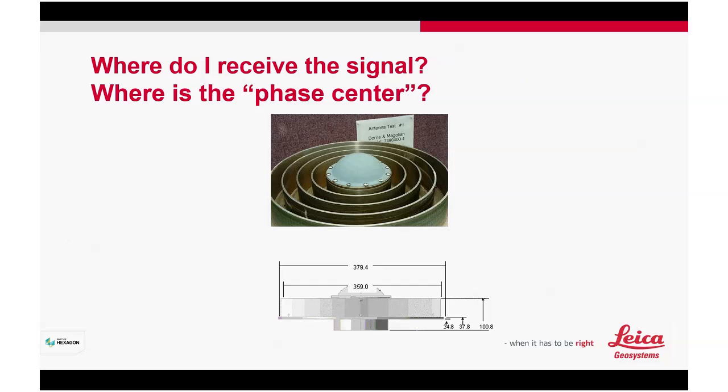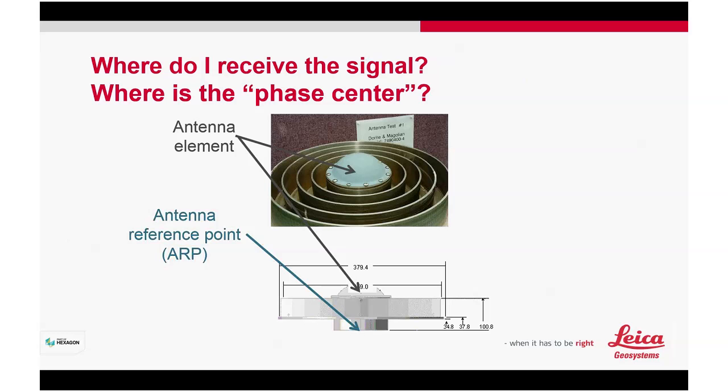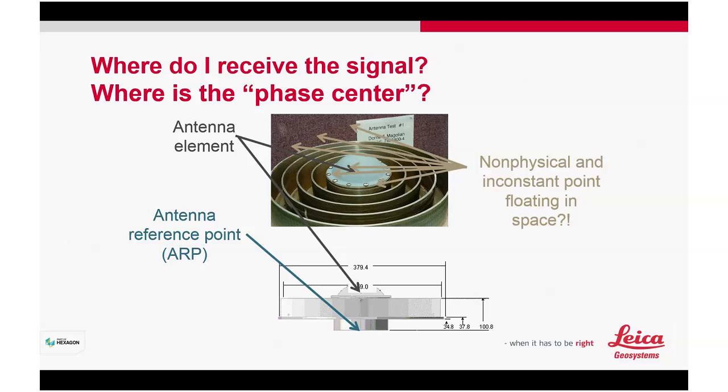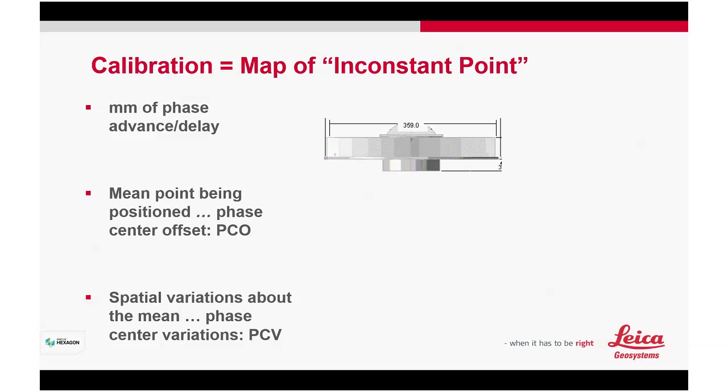Okay, so you see the antenna phase center. Okay, the question is, where is the signal we receive by this antenna? Okay, and then we have a so-called antenna reference point, or for us we call it the mechanical reference point. Okay, so there are those parameters we need to define well. And organizations like the NGS, like Geo++, are doing this measurement and define where the offset is, the phase center offset, and how good your phase center is. Okay, so there is talk about the accuracy of this phase center.